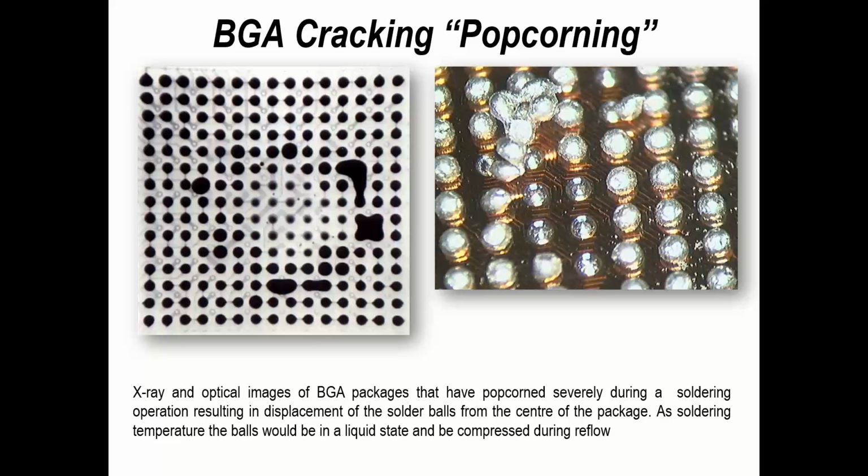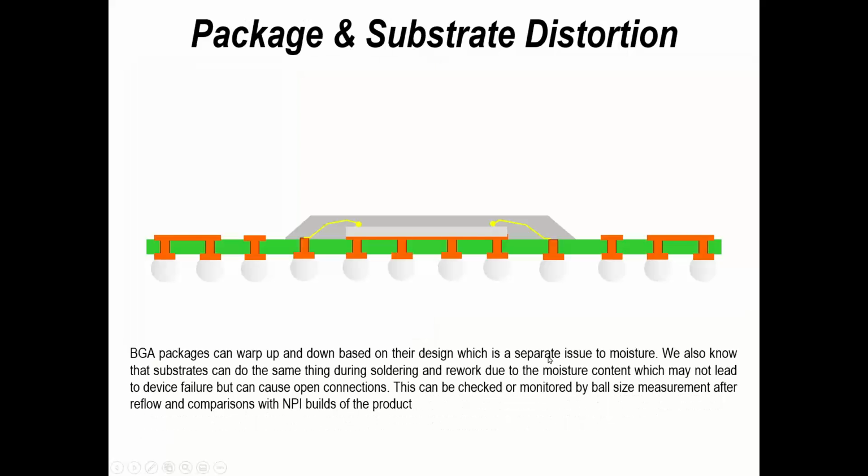Here, again, we're showing the phenomena of failure. In this particular case, the reaction due to the soldering temperature plus the moisture was so severe, it literally squashed nearly all of the spheres in the center of this package. And when the package was mechanically removed, you can see that the balls have been displaced. So that's sort of a before and after situation, but again, a nice illustration so you understand what's actually going on in the process.